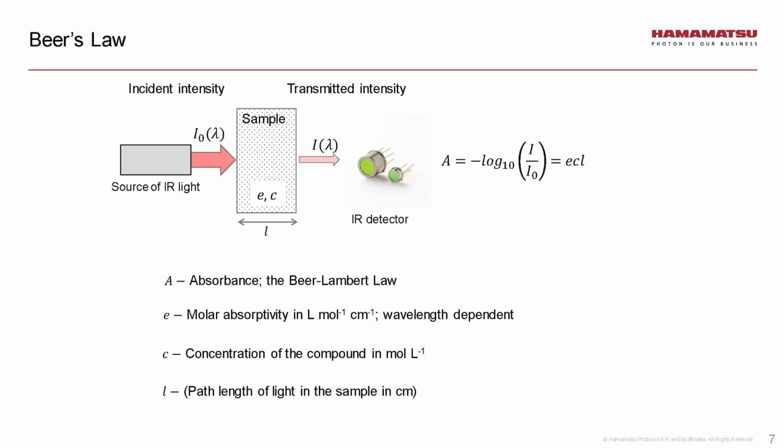And putting it all together, how are we going to measure a gas using light, mainly infrared light? You have an IR light source that is producing these wavelengths, and then you have your sample, the gas, and as it absorbs this energy at that specific frequency or wavelength, you're going to get a weaker signal. Then you see this change in signal with an infrared detector. All of this feeds into what we call the Beer-Lambert law.